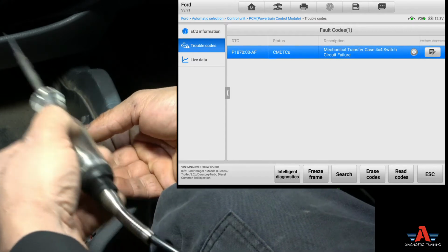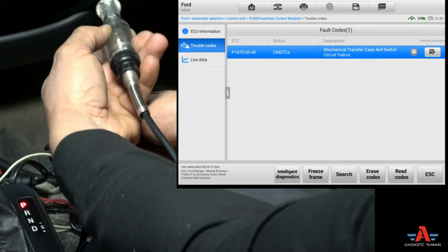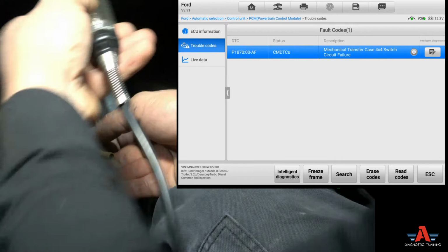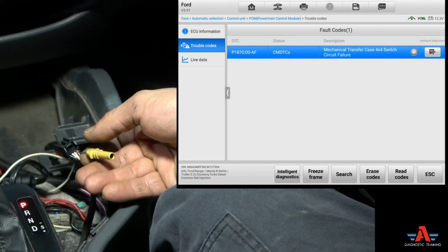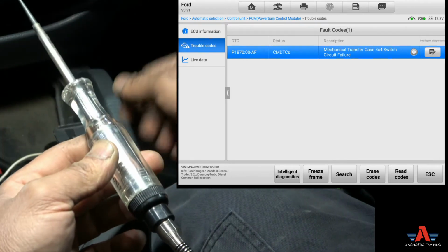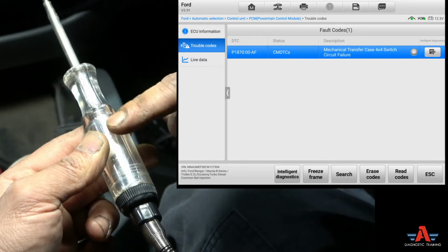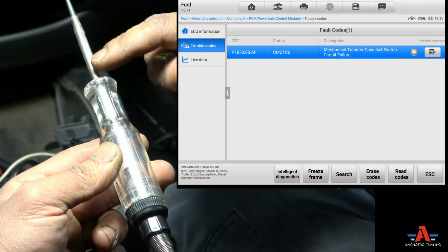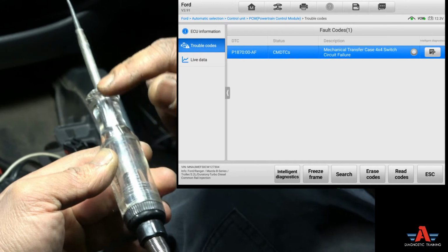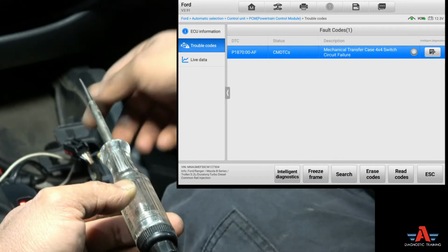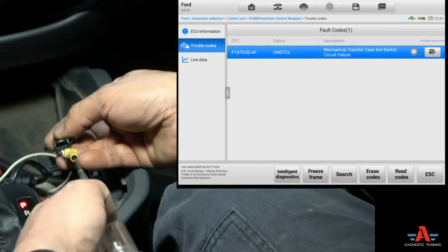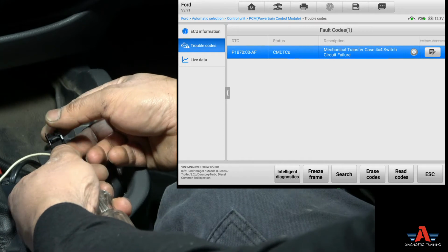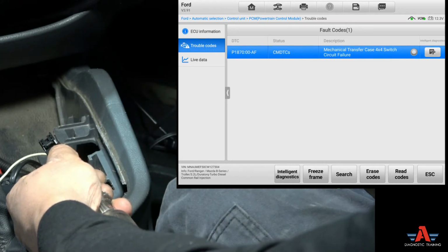Okay, I'm just going to make sure my test light lights up. My test light is connected to battery negative. Now I got earth traveling through the coil and through the resistor in that bulb onto that tip. I got earth, so I'm just going to touch and back probe that signal wire now, and let's see what kind of fault we get.